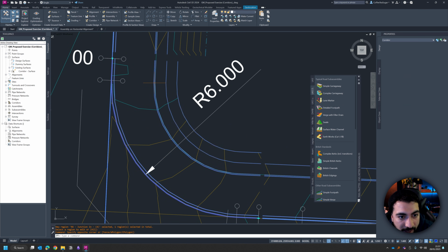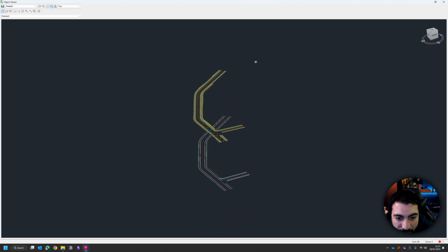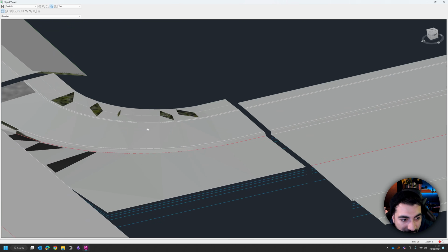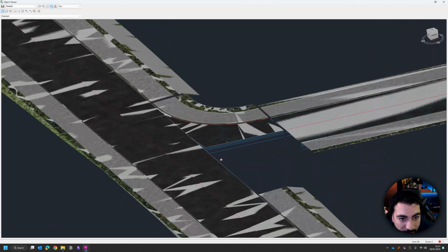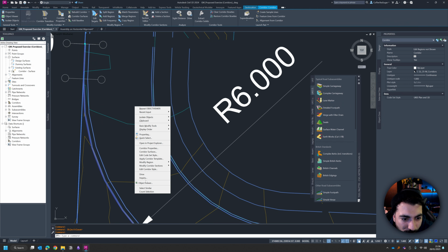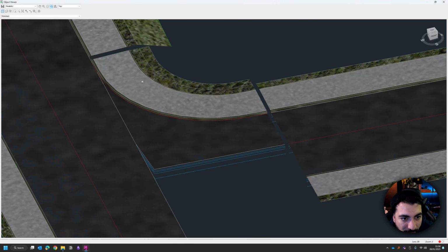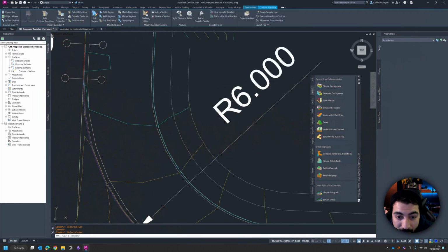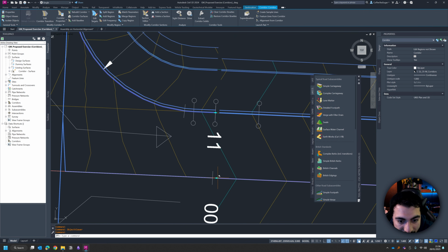And if I go to my 3D model right now with the corridor, I think I should have selected corridor, but you can see we have still some gaps in the corridor model. Is it some gaps? No, I think because I selected the corridor as well. So let's just do the corridor only. So it looks absolutely fine. Now you have a few minor gaps. That's absolutely fine. You can just extend the grips. So I'm going to extend the grips from there all the way to there.